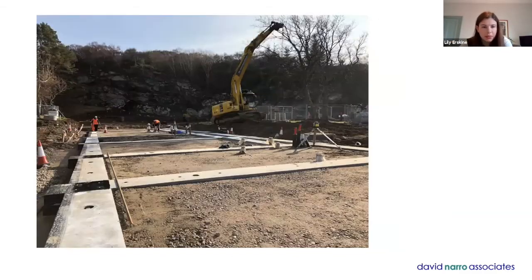So we ended up developing a system of precast beams. Now, precast, as was previously mentioned, generally has always been grouted together, and that's where you get your robustness. So you have a series of parts, generally cast with reinforcement sticking out the end, and then you glue it all together. Now, the same with in situ concrete, that doesn't work in a circular sense because you have to destroy it in order to reuse it.